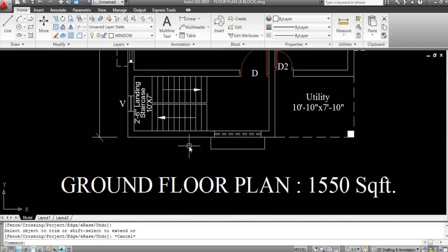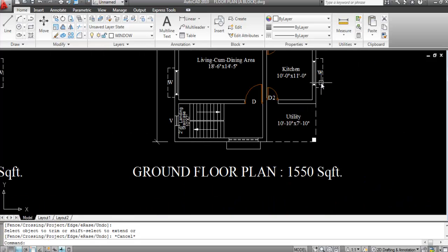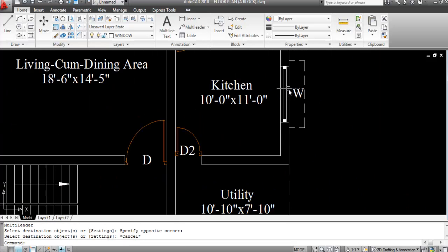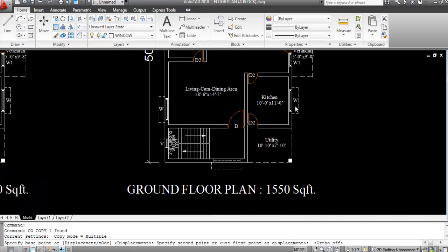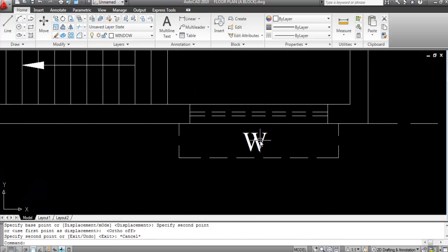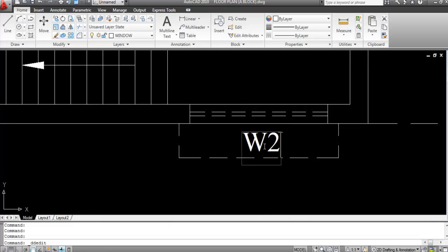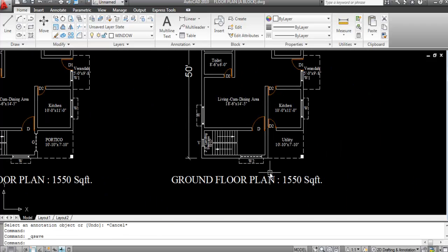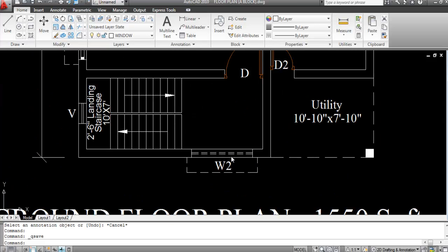Now I'll do mesh properties of chassis. So this is chassis. Select MA, enter. MA is the shortcut key of mesh properties. Now this is done. Now copy this. So this is W2. Rename this as W2. Okay. So this is W2.